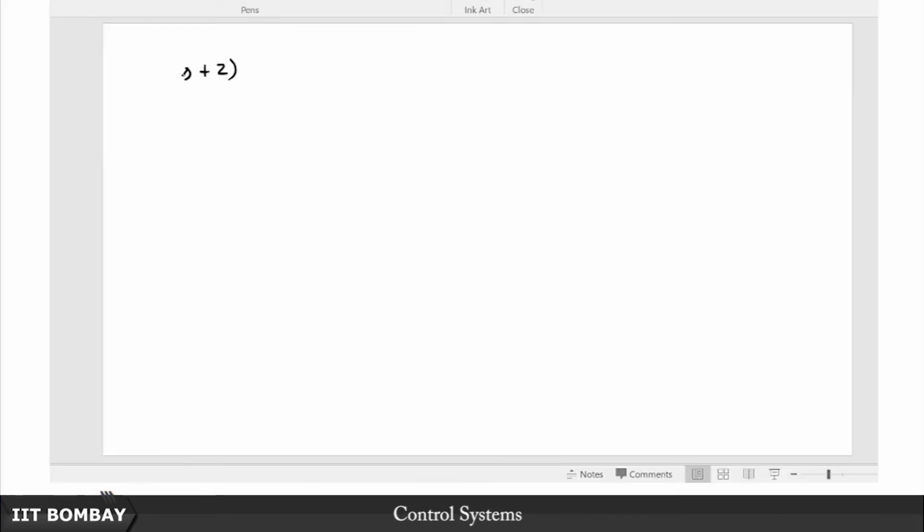That is one of the musts. The steps will be very similar. The only things that will change are at some subtle junctures, and you will see why those changes come in. The moment you introduce this PD block, it has a transfer function like s plus z. It's an improper transfer function to start with. Also, apart from the fact that it requires active elements to implement, there's also this factor that PD controllers can be noisy. Why do I say that?